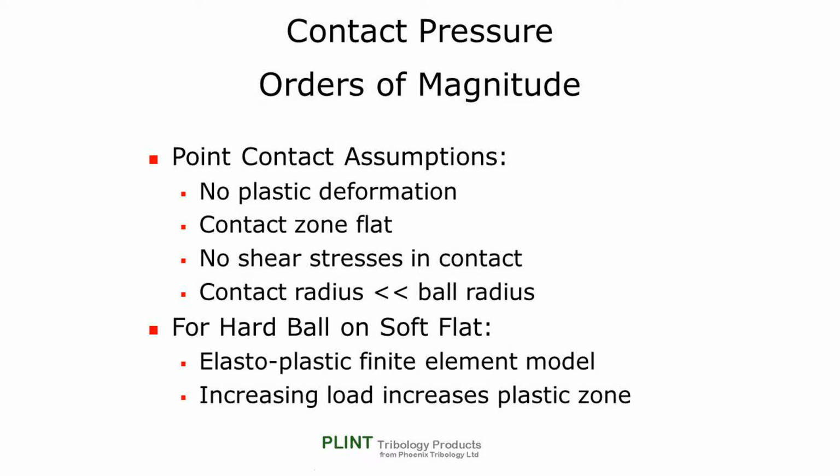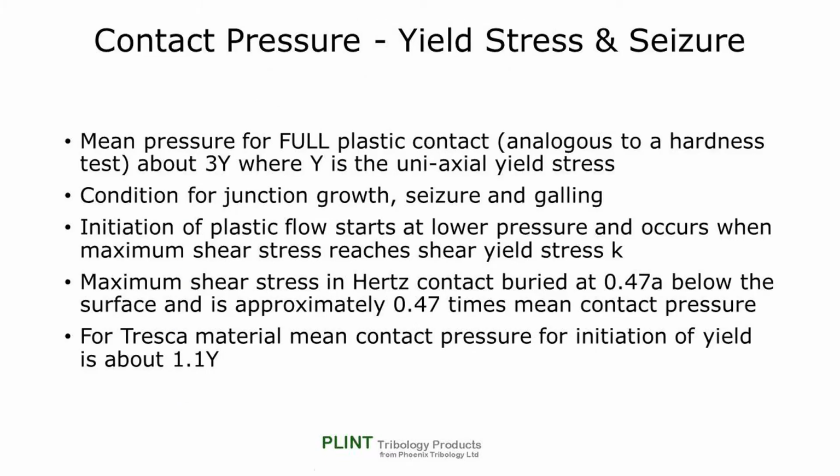This will not be the case if we have a hard ball loaded against a softer flat, where plastic deformation may take place. In this case, we cannot sensibly use the Hertz equations and instead must use an elastoplastic finite element model to evaluate the contact conditions.